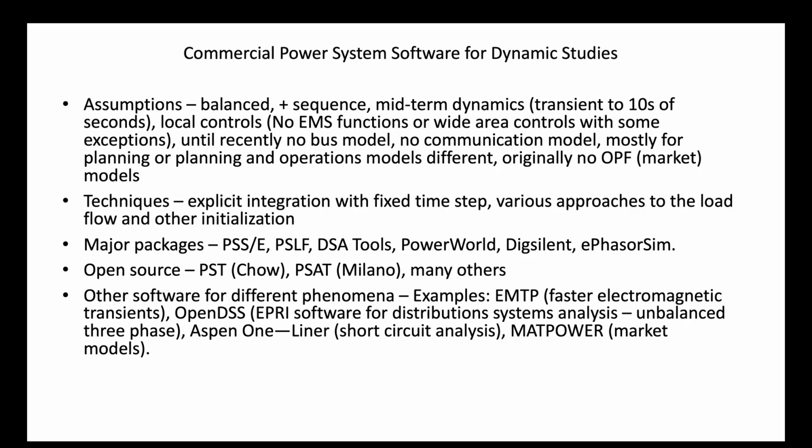You get the layout of the transformers, and also the bus protection, usually something called breaker and a half, which is one of the types of protection schemes. It tells you where on the bus bar the breakers and transformers are located. You need that if you're the operator, because when you're taking action, most of the time it's switching things in and out. So you've got to know what the layout is at the substation.